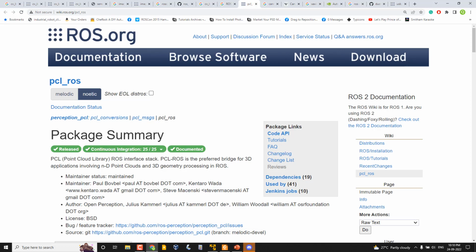Then, sir, what will be the proper flow when considering any constrained embedded device? Yeah, Trishant, choosing the right computer is actually difficult even for me. I'm not saying I know everything. I'm still learning, I'm still a student. But from my experience, one of the major constraints is the cost itself, because we can't include an Orin or Xavier board in a low cost robot.